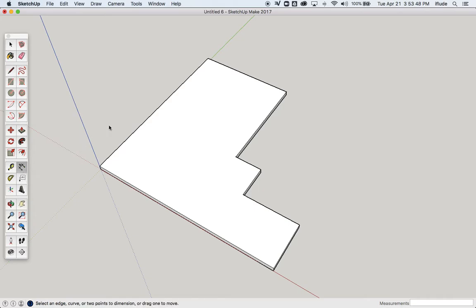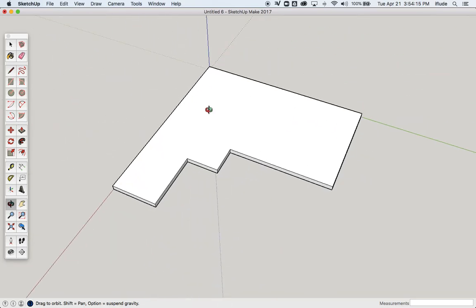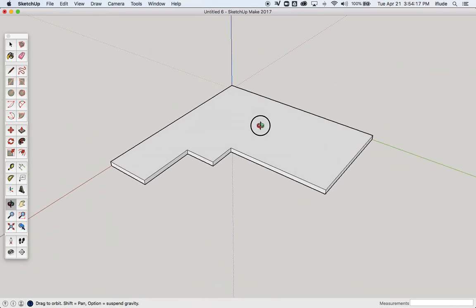And my tip for using this successfully is to start off with the biggest dimensions on your product and dimension them from one specific point. So you're going to have vertical dimensions and you're going to have horizontal dimensions. Now, it could be horizontal, vertical, vertical, horizontal. You're going to have dimensions in two different directions, especially if you've got a product that has straight sides.